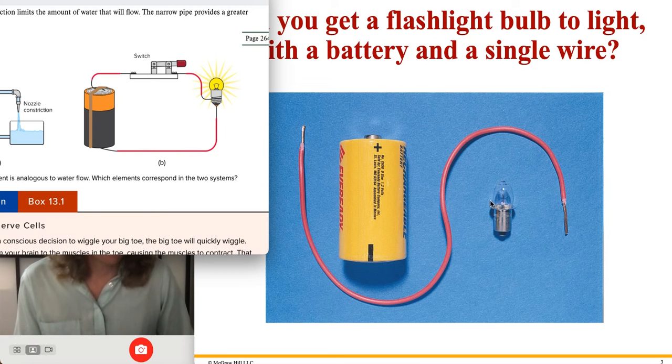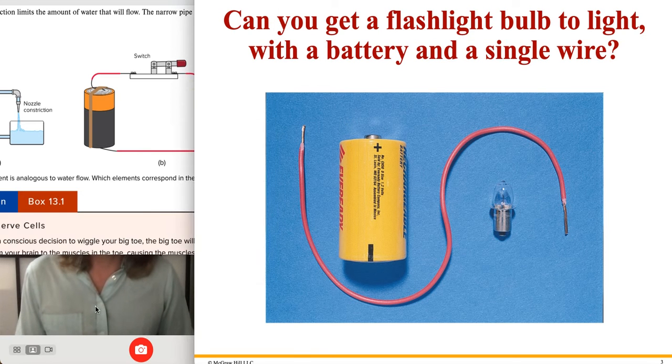So there's basically a hollow cylinder of insulation that runs all the way up. That means there's continuous metal that would be connected to one part of the actual resistor, going into the bulb, and we have a cross-section of it later on. And then it would come back out the other way, not touching that metal again, and come out the bottom. So there's a path that comes out of the little metal bottom part shown here, that is insulated and able to run through the exterior metal part. So it's an actual continuous path, right? Because otherwise it would just short itself out, okay?